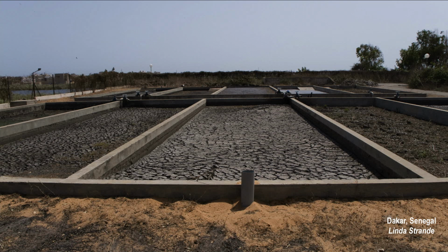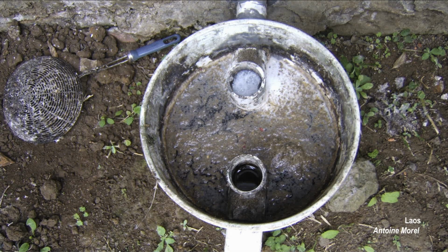discharged into the environment. In the same way that sludge settles to the bottom of black water, lighter particles will rise to the top. Fats, oils, grease, and surfactants, FOGS, is the name given to all the frothy scum that floats to the top of a wastewater, particularly gray water. FOGS generally comes from the cooking fat and soaps that are used in the kitchen.